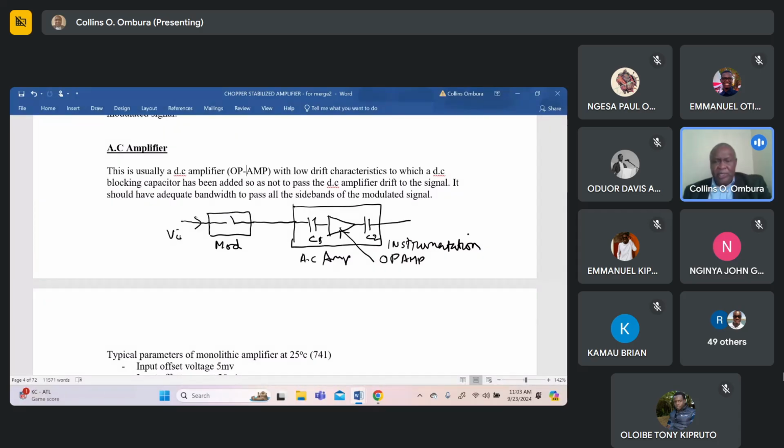And similarly, let's assume we only consider a normal AC amplifier. Let's assume this was our AC amplifier, and we ground the input, and we design maybe a negative feedback amplifier. We ground the input so that there's no signal. Now, we can get an equivalent circuit of this voltage over here, the drift voltage, which you call VAO. And even if you ground this, you get an output voltage over here, which would be minus RF over RI into VAO.